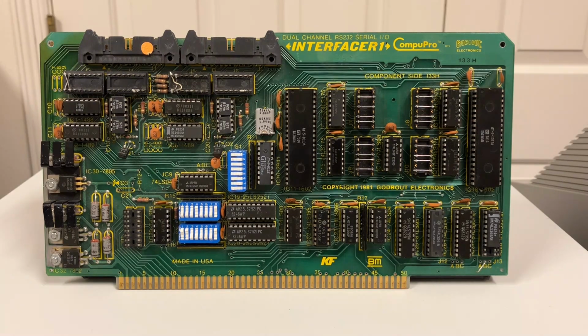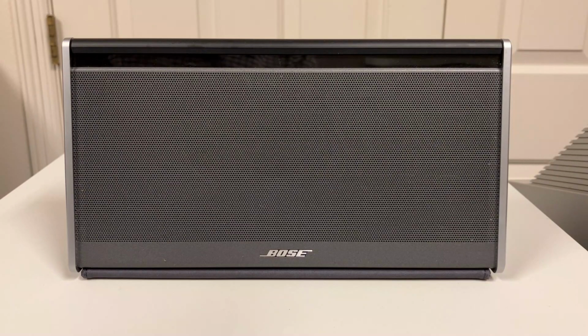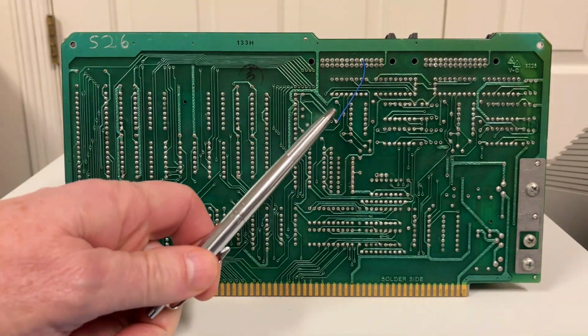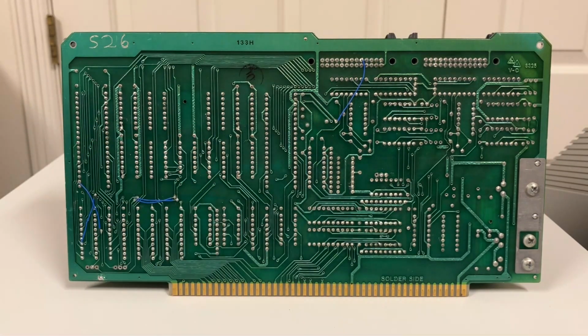And of course if you're going to hook to a terminal, you want your computer to be DCE. All right, so at that point, this does everything we need to hook to a cassette. Now, as before, I'm going to want to add 5 volts onto pin 18 of the DB25. And that's this blue wire you see right here. That's going up to the IDC connector, hooking to 5 volts that's on the board. With that in place, I have the 5 volts to drive the modem.